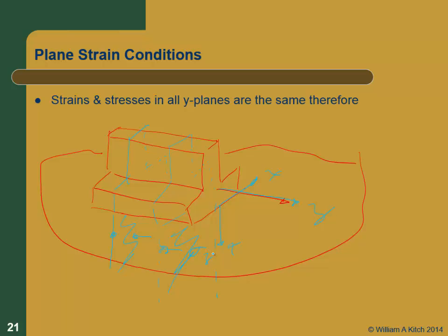So what about the shear stress? What about any shear stresses that are in that plane? Well, there can't be any shear stresses. There can't be any shear stresses in this plane, because if there were, those two planes wouldn't be acting the same. Or in this plane, there can't be any shear stresses, because then we wouldn't have the same conditions at those 2 points, right?